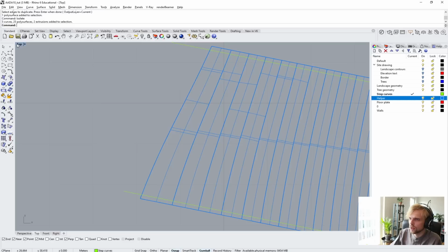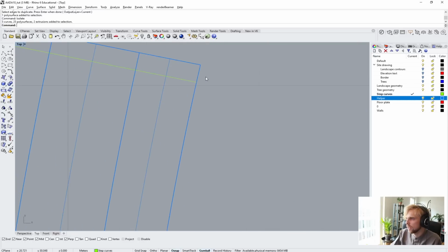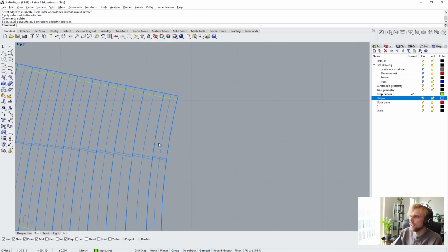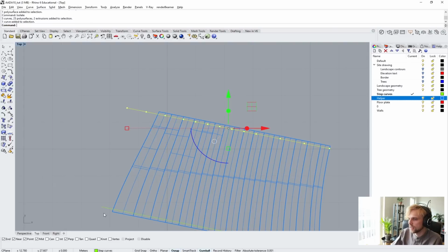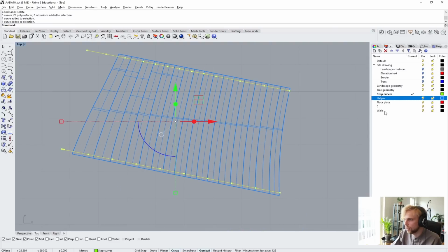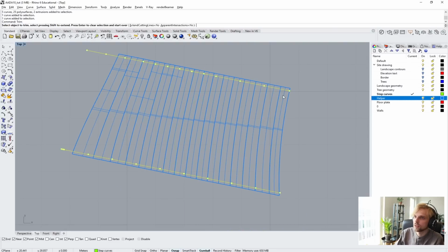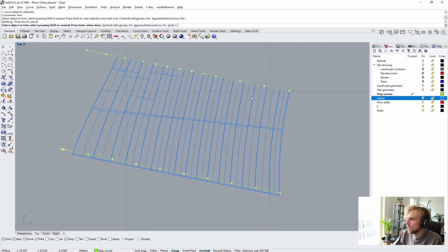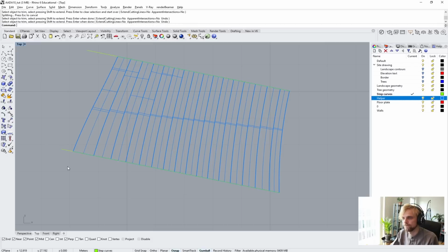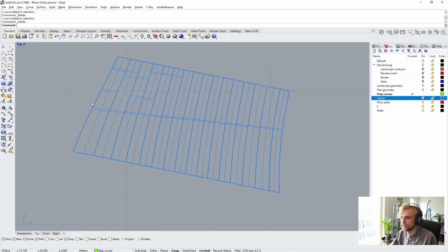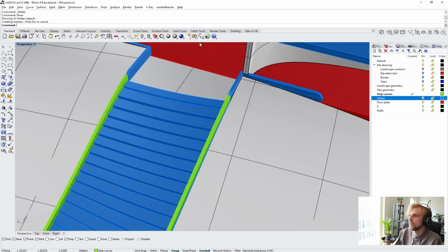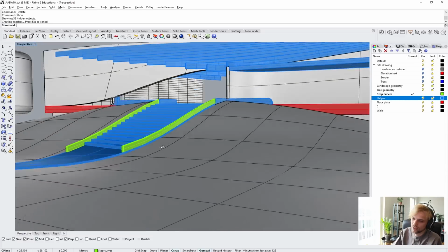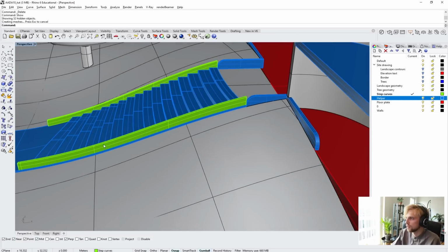I can go to the top view. And here I just need to make sure that that seems okay and that seems okay. So I have two edges that are definitely cutting through the staircase. So then I can just use them to trim this part and this part. That's it. And then I just delete them. Use show. And now this should be kind of, let's call it clean enough. Not clean, but clean enough for this to work.